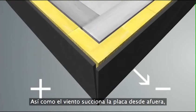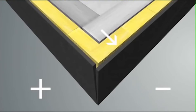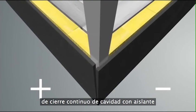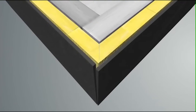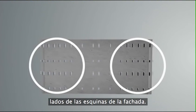As well as the wind pulling the panel from the outside, the back of the panel can also be subjected to pushing from the cavity. To counteract this, a continuous vertical cavity closer is introduced so that the wind pressures are separated. Another solution is to fix extra supports on both sides of the corners of the facade.